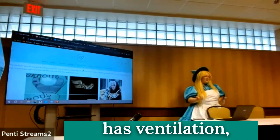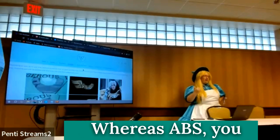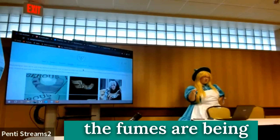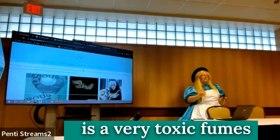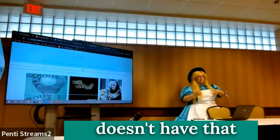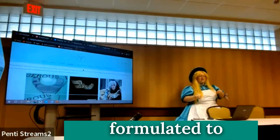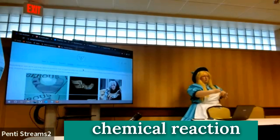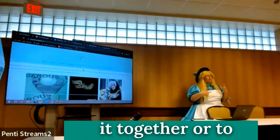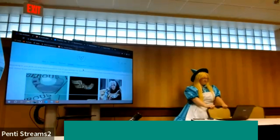As long as the room has ventilation, it's not as big of a concern. Whereas ABS, you have to have an enclosure. You need to make sure that the fumes are being extracted, because it is a very toxic fume that is released. Unfortunately, PLA doesn't have that chemical reaction. There are products out there that have been specifically formulated to have that kind of chemical reaction with PLA to help you bond it together, or to be able to do that chemical smoothing.